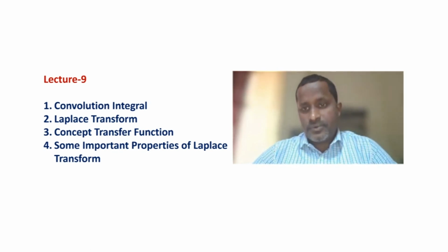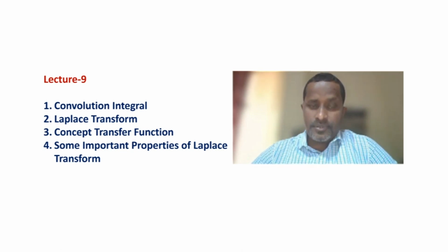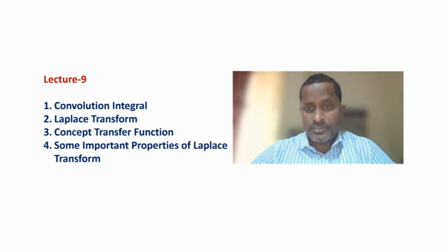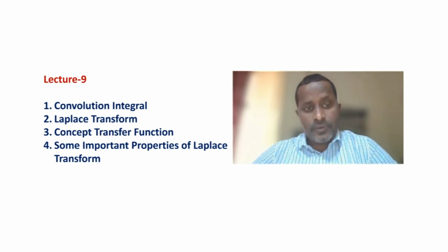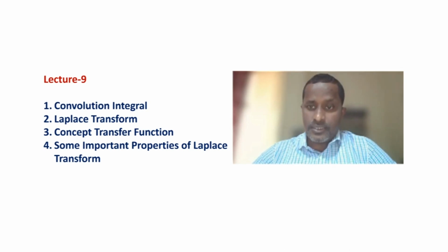Also, we'll be discussing why we have to assume zero initial condition for finding the transfer function, because if you assume non-zero initial conditions, the principle of superposition cannot be applied. Then we'll conclude the lecture with some important properties of Laplace transform, which we'll be using in later lectures.